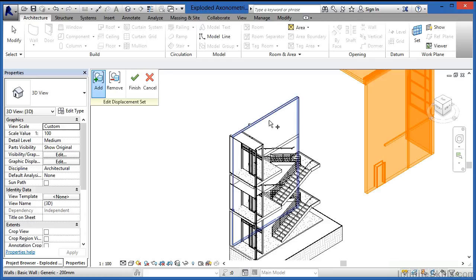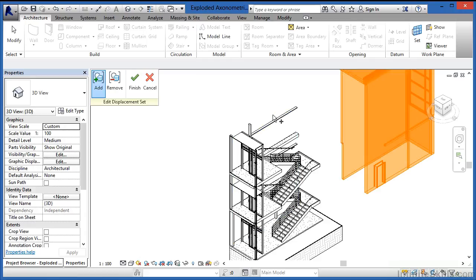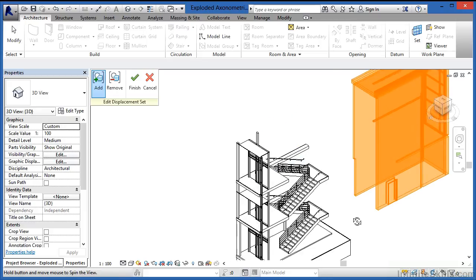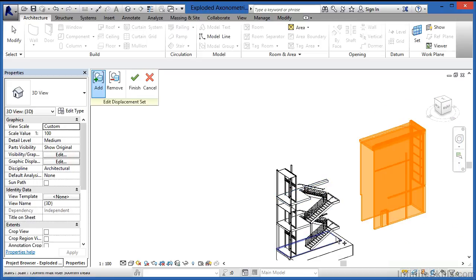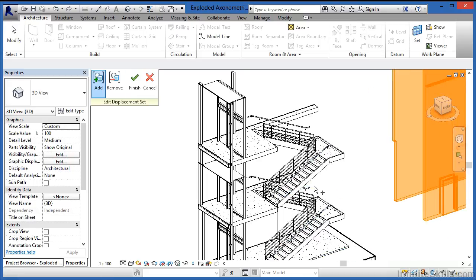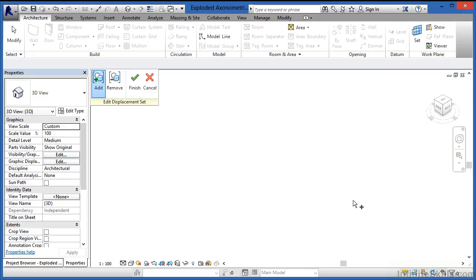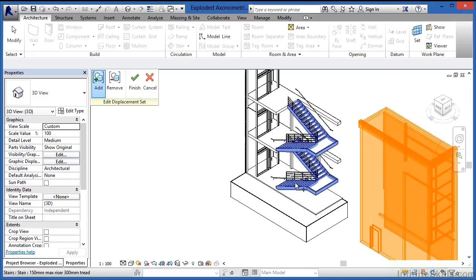Now, all I'm doing is selecting these individual walls to pull them away. I'm going to click here, click on this piece here, and there should be another one down here somewhere, so I'm going to go looking for it. Select this piece here, and have it get pulled away. It looks like it's just a tiny little wall, so I'll get rid of that too. Now I'm going to click on a corner of the view cube to spin this around. I'll zoom in a little more tightly and pick each of these, and we can see them getting dragged immediately over here.